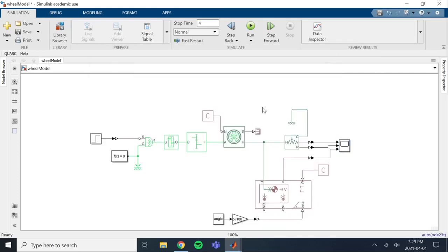Now this is only with one tire right now. So what you can do is basically just copy and paste this. We have 6 of these setups in our suspension. So what you do is just put 6 of these in parallel, connecting up the physical signals all together, and then connecting up the grounds all in the same place. So the solver is connected to all of the torque sources. And then the outputs here for H are all going to connect to this same line. You don't need any more of these sensors. These sensors are basically useless now that we have this Rover body.